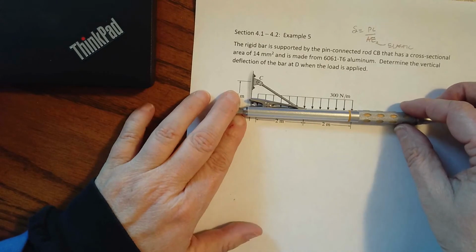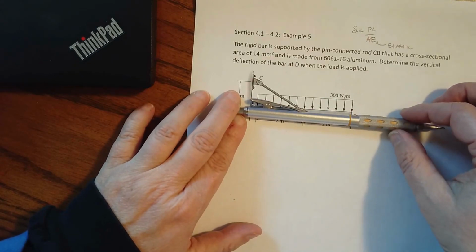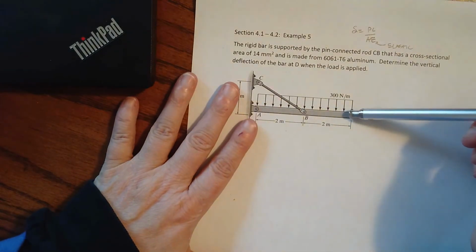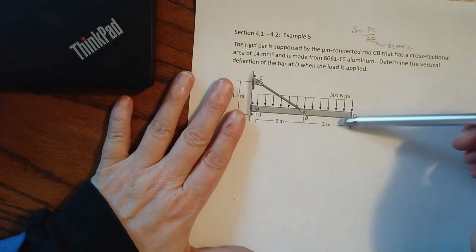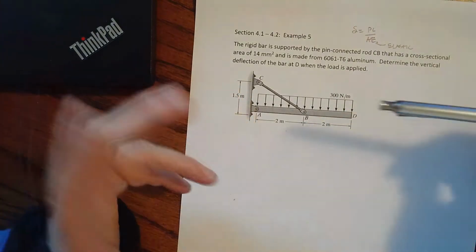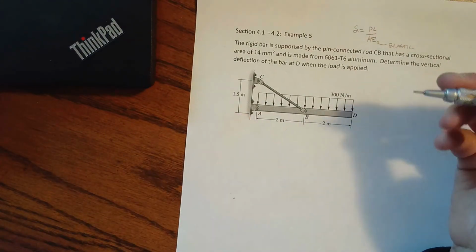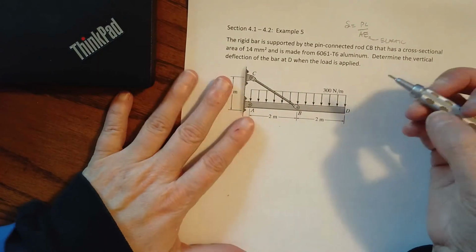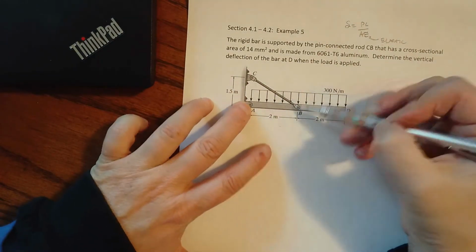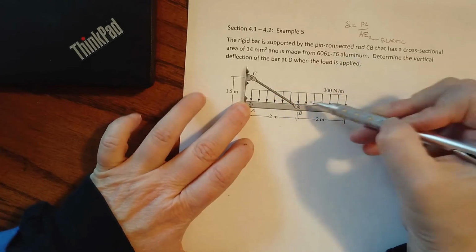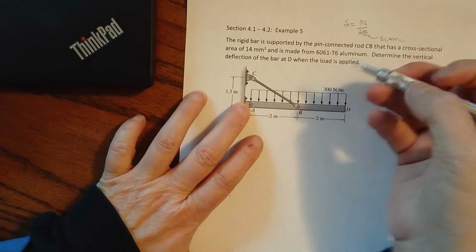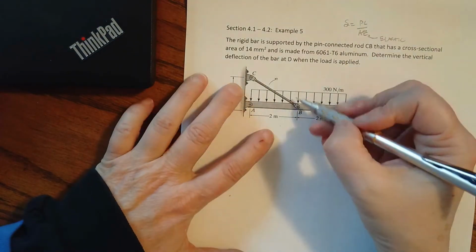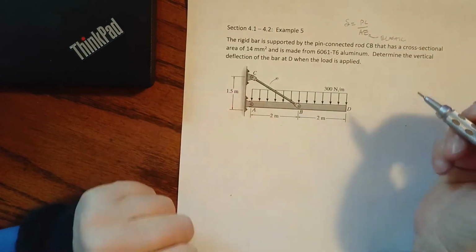So you have to remember if we are in the elastic region, as we have just this slight rotation, the displacement we can consider to be in the vertical direction because there's insignificant displacement in the X direction, which makes it a much nicer solution. Okay, so we're going to be looking at that vertical rotation coming straight down. As I apply the load here, we have a pinned connection and a pin connected rod that is in tension. So as this stretches with that rotation, if we can figure out what's going on here, then we can relate it to the end.